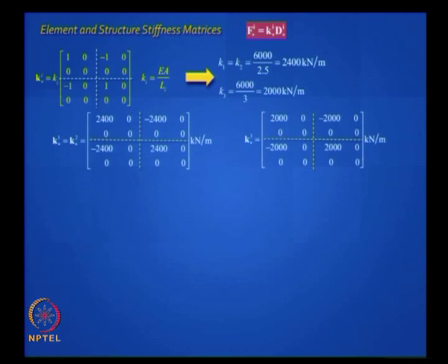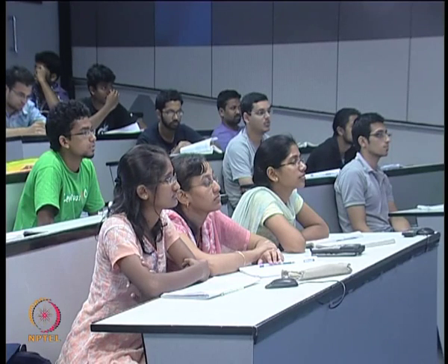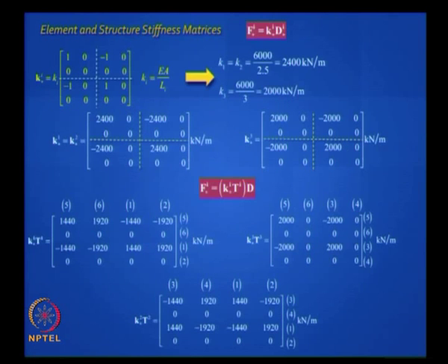Now you have to do the slotting business. So can you do it? Yes, we went through this exercise. You can do it. You first calculate Ki star Ti and put the linking coordinates and put the units also. All stiffnesses are kilonewton per meter. You got Ti for every element, you got Ki star for every element. Can you not do the product? Can you not put the linking coordinates? What's the next step?